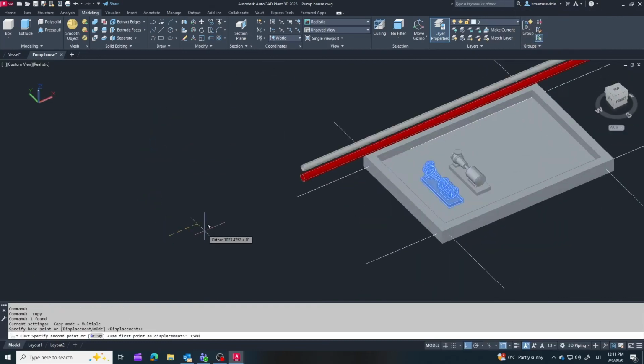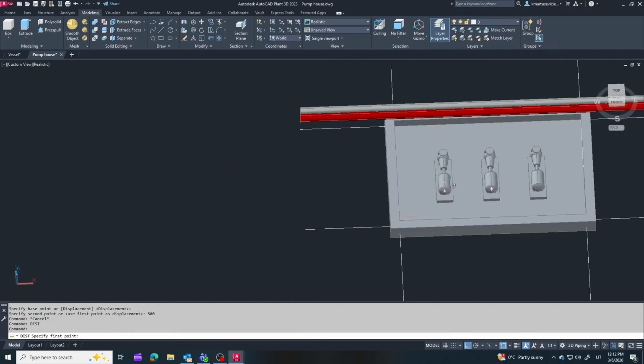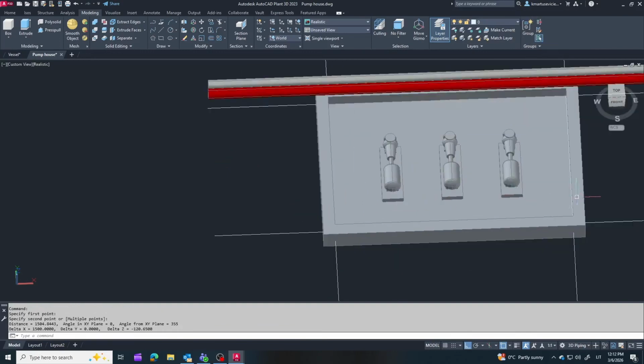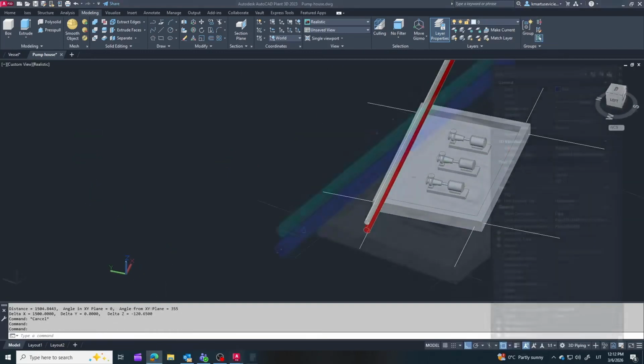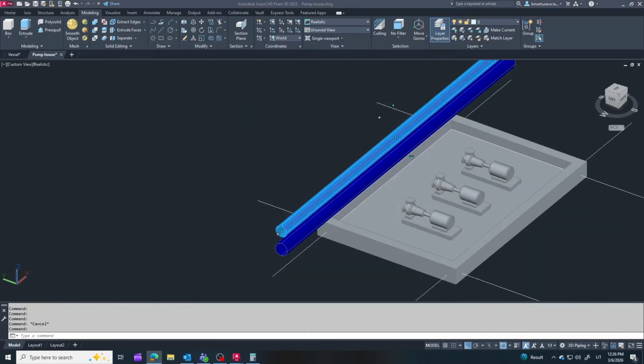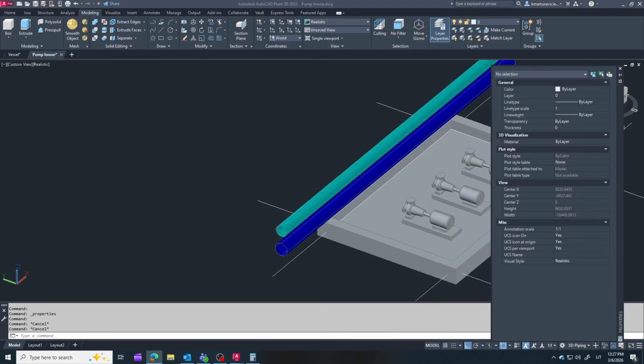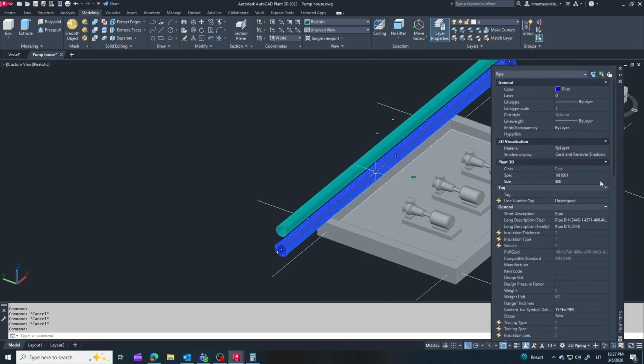My idea is to use pumps with DN250 suction and DN200 discharge nozzles. Since I have 3 pumps, I need to recalculate the manifold sizes. I sum the cross-sectional areas of the 3 branch pipes, and then convert that total area back into an equivalent manifold diameter. This gives me approximately DN450 for the suction manifold and DN350 for the discharge manifold.